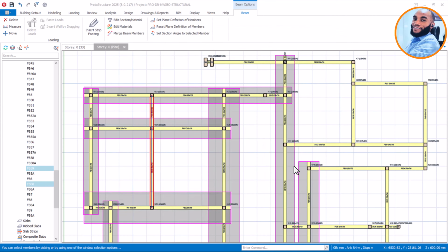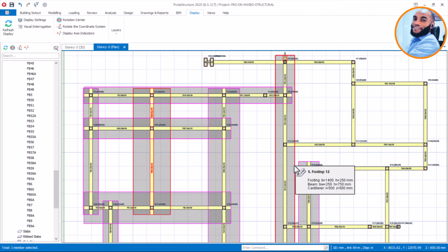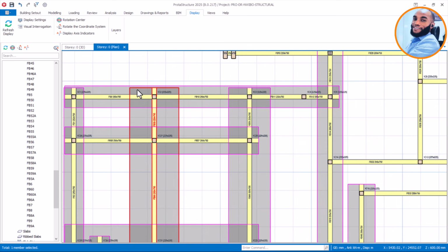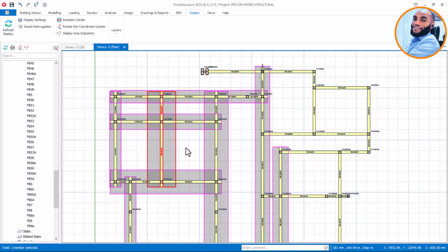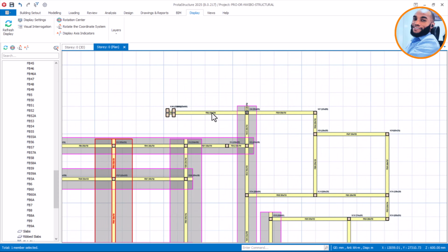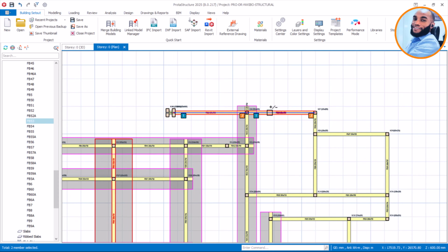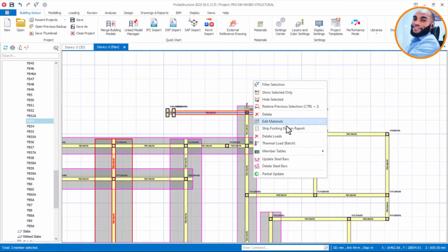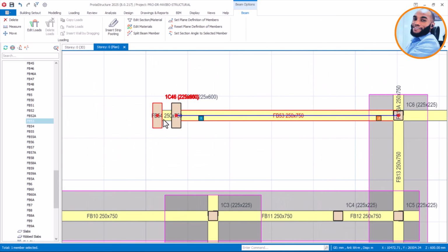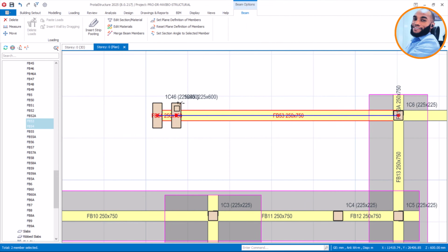Now when it's getting bigger, for example, you're having like 5 meters as the footing width, that's very too big. What it means is that strip foundation is no longer advisable to be used. So it is good you move to other type of foundation, which is a beam raft foundation.